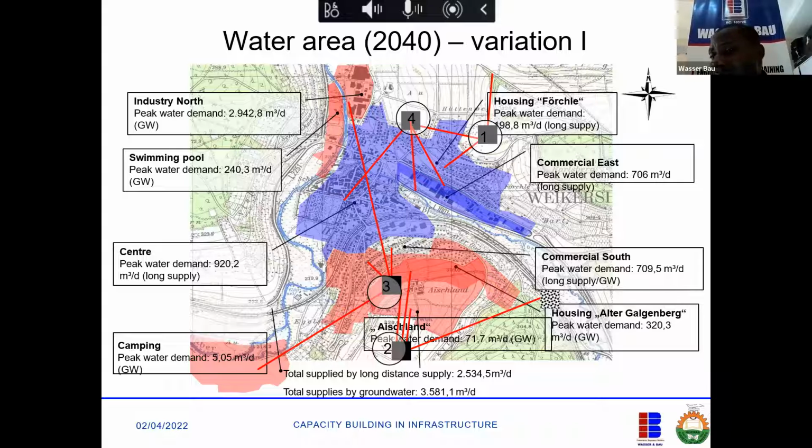or phases. Phase 1, you do a design for them. Phase 2, you do a design for them. But even if you want to do one common design, then you must have a holding tank. The idea is that in case of maintenance, you don't shut down everybody. I know in Abuja, when they want to do some maintenance, they specify which area, and they just go turn off the valve, and ask those people to prepare water ahead of maintenance.